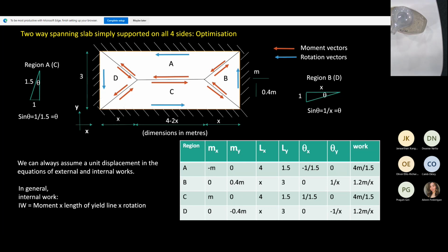So if you use EC2, if you know all the dimensions of the slab, the thickness, and you know the reinforcing bars and the diameters and everything, you should be able to work out the moments of resistance using Eurocode 2. But we are not doing design, so I will always give you these values for the particular problem. Okay, but you can actually get them if you know everything about the slab, from design. Okay, do you agree with these projections now for B, please?